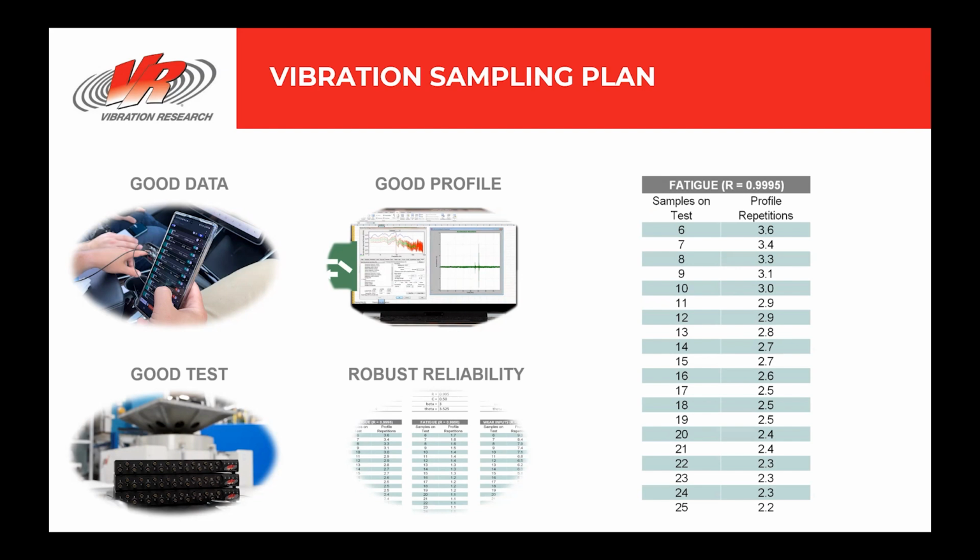For example, if the test is designed specifically for a solder failure, but a different failure occurs, an appropriate iteration of the sampling plan can be applied to determine if the product had already achieved the reliability requirement for that failure mode based on the sample size and repetitions. Please note that the sampling plan shown here is only for illustration, and that results will differ depending on the product, its intended service life, reliability requirements, and specific failure mode of interest.